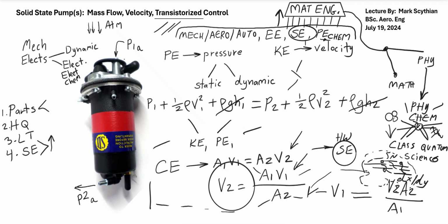velocity, and just the general pump designs, whether they are mechanical, analog, electrical, digital, solid state, etc., is the understanding that fundamentally we're dealing with pressure as potential energy, velocity is the kinetic energy, and then if you visit the Bernoulli equation, you see that the first rho GH is going to be correlating to mgh, or potential energy, on the input side, along with the output side, rho GH2, and conversely the 1/2 rho v squared 1 is going to correlate from the input side to the 1/2 rho v squared 2 on the output side.